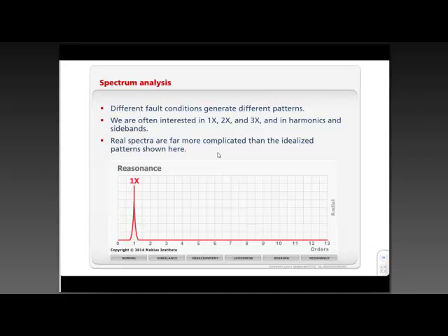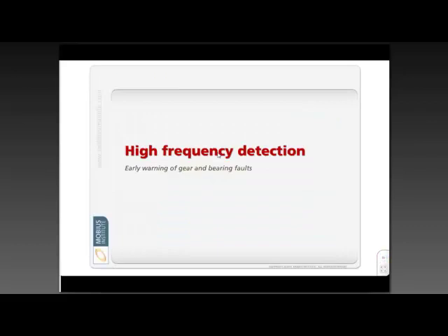You know, we can make good decisions with the spectrum alone, absolutely, but the machine is telling us much more, and I think it's wise for us to listen to everything the machine is saying. So the spectrum's great, it's a simplification of the vibration, but we can go further. The first thing I want to mention is that we can specifically listen to very high frequency vibration.